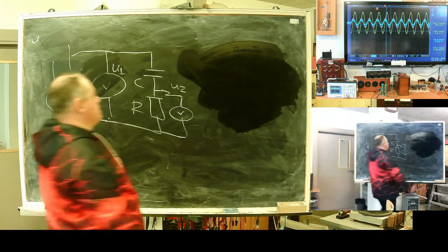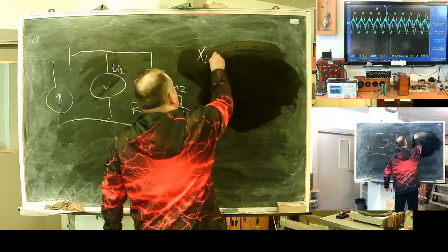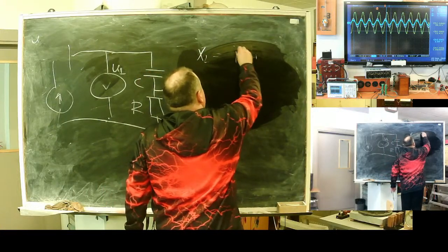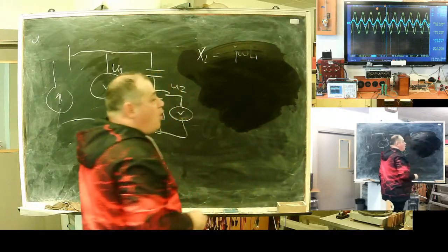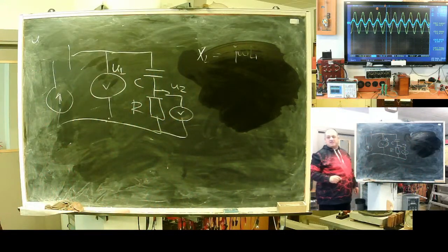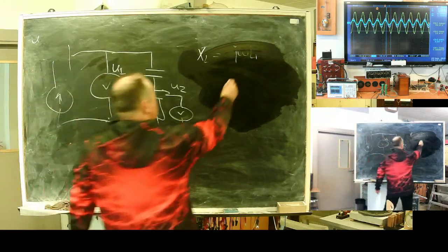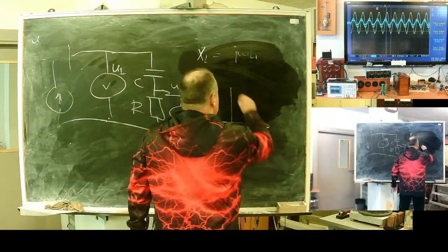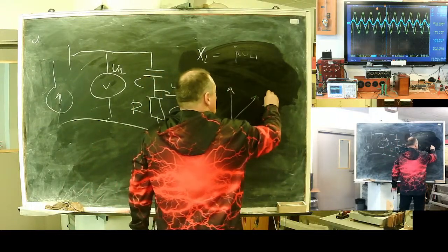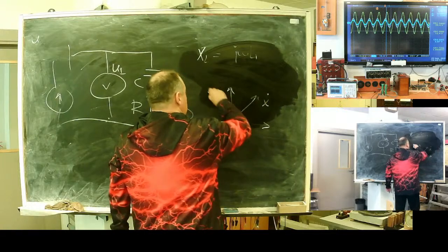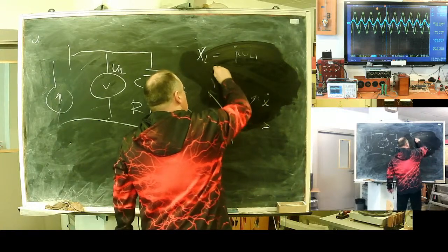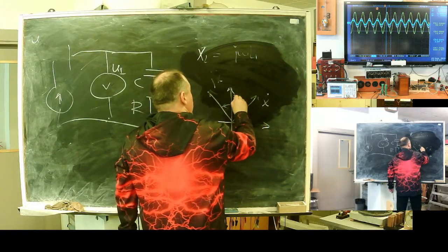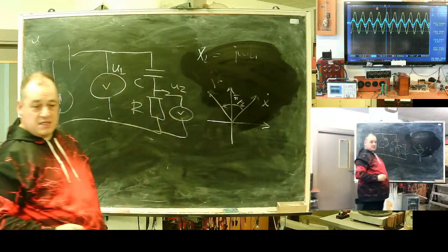So the idea is, for the coil, XL, j omega L will be used. It's a complex or reactive resistance of the coil. This multiplication is done to reflect cosine. The idea: if you have some complex number, multiplying it by square root of -1 means turn it forward by 90 degrees.